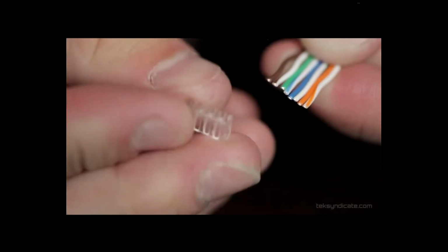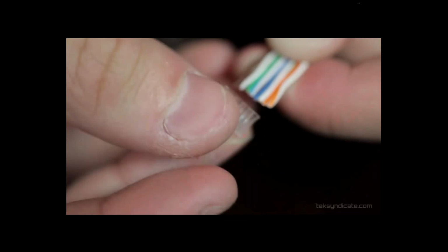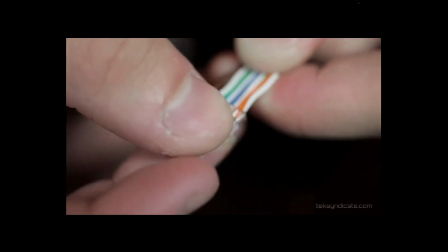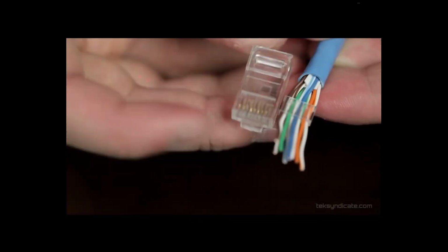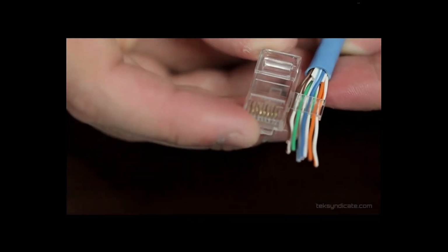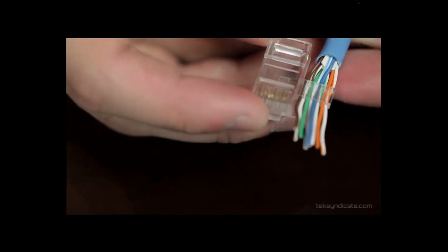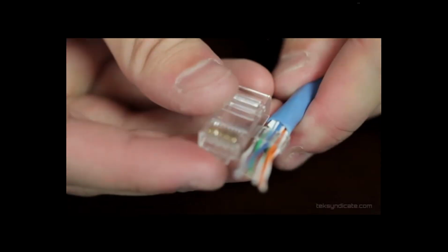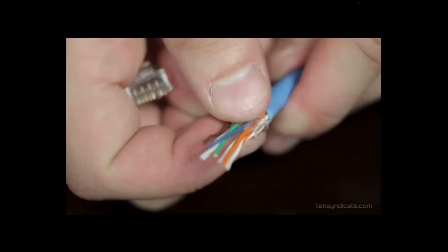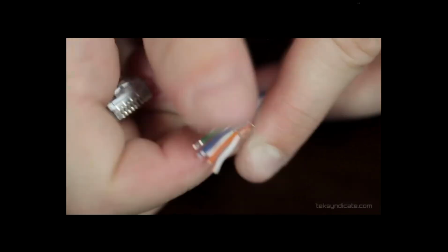and we want to put these into this connector, and they will find their way right to where they need to be, if I can get them all in there. Wiggle it around a little bit. This piece and the finished product will end in the conductor, or the modular plug, right about there. So we want this as far down as we can because we want this piece to crimp the sheath. So what I usually do is I measure out where I want this, put our little pieces all the way to where we want it, to measure the length.